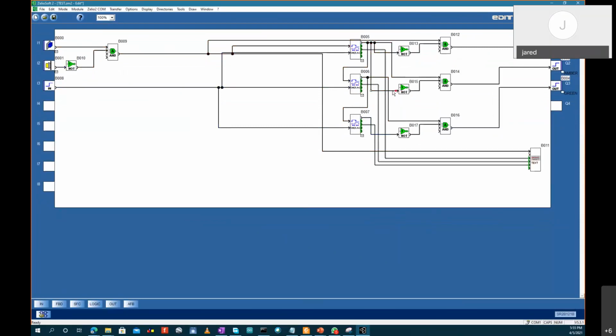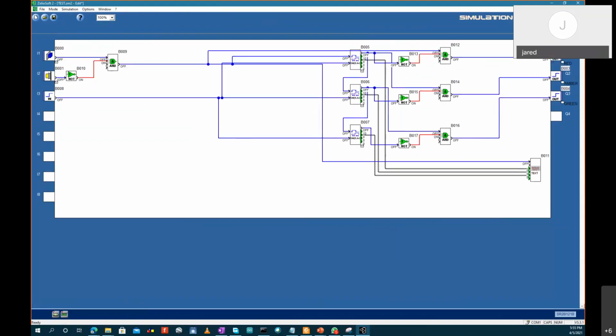Yeah. So this done should not come from here. The signal should come from this one here, because it's associated with that one. So now it should run. So sometimes you need to debug your program. You need to step through it, and you can save as versions if you're dealing with a big, complex PLC program. And you can start.